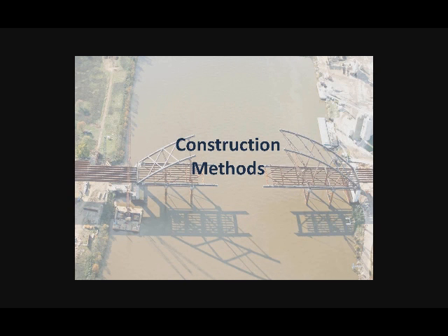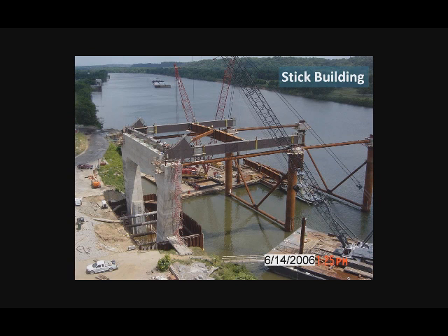Okay, so now we've done the erection engineering. It's out of the way. Let's look at the actual construction. And as I mentioned earlier, arches are interesting in that the construction stages are very different from the final stage. I want to run through just a few methods. This is the first one, which we call stick building, where each component is simply delivered to the final location